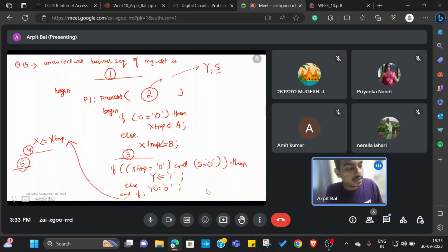Let me write the conditions which need to be fulfilled so that the variables can be placed in a sensitivity list. Either they appear on RHS of a process statement, or if they appear on a comparison.